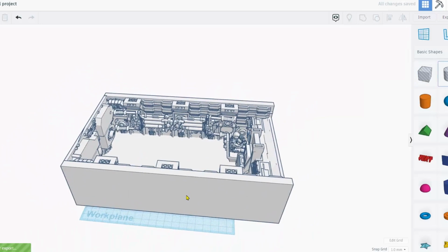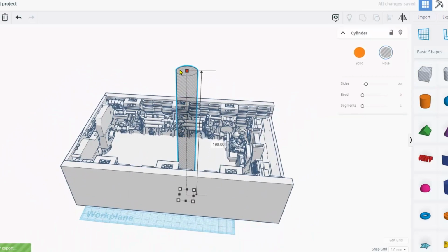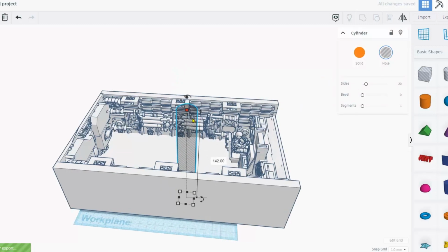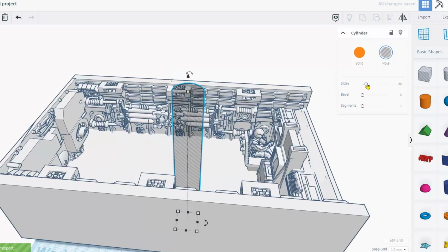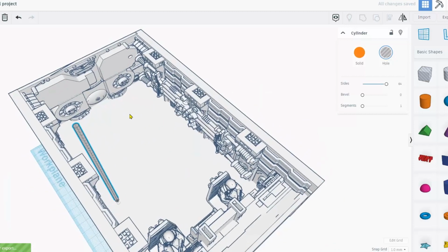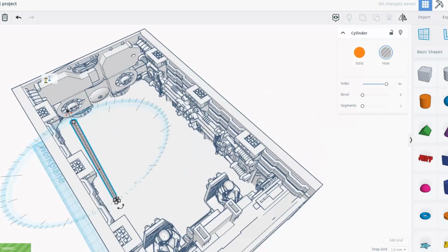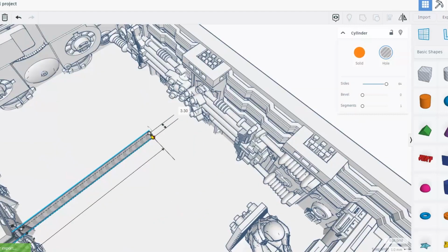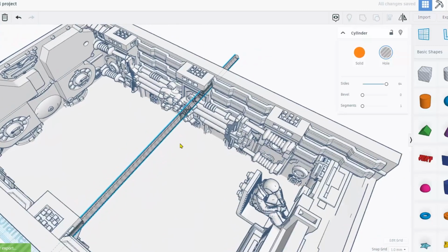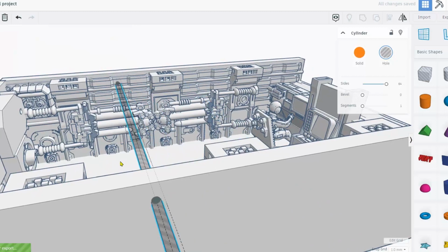Oh, and one more little tip here. If you're designing this to light with LEDs, you can pre-drill your LED holes, getting them ready for lighting. So let's do 3mm LEDs. We want a little bit of tolerance, actually, so we're going to make it like 3.3. Turn that on its side. And just so we can make a bunch of holes all at once, we're going to duplicate this and kind of repeat the pattern.